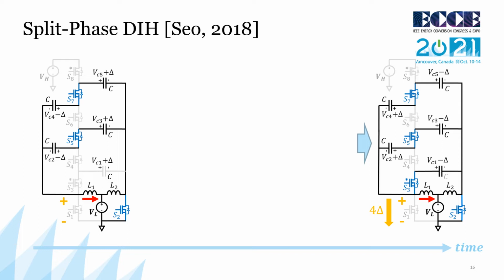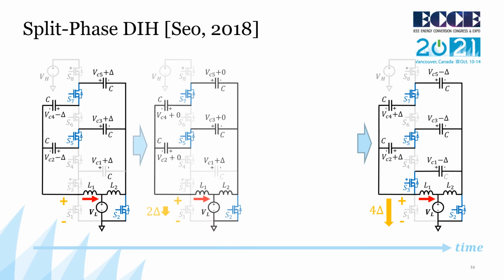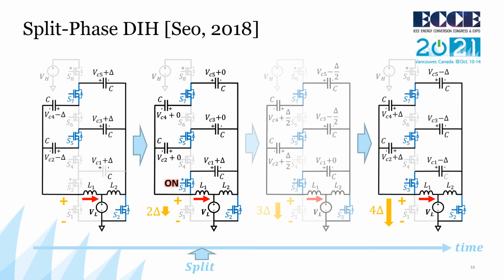So it makes sense that we should only include our single capacitor branch after a 2 delta swing has elapsed and while there still remains an additional 2 delta swing for it to partake in. This is the moment at which we switch in our fly capacitor, where it then continues with the others until the end of the phase. In this way, we have successfully soft charged all of our fly capacitors with no jarring and abrupt hard charging transitions. But there is still a limitation here.